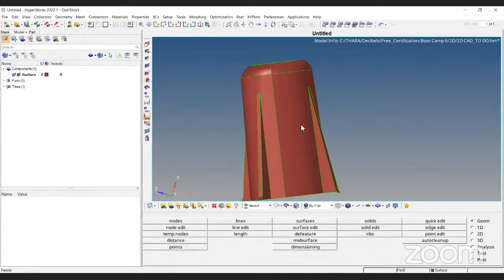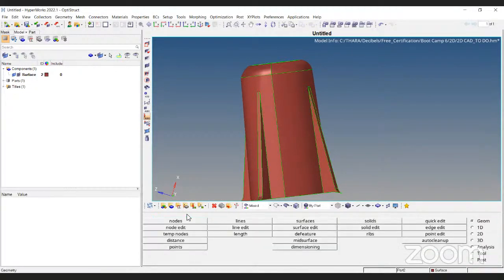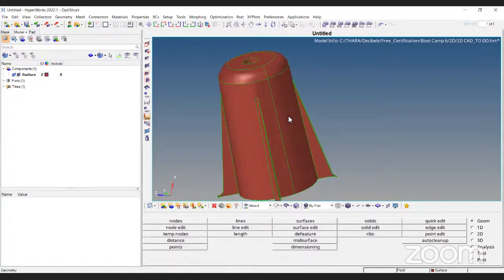And HyperMesh has function keys from F1 to F12, which are different shortcut keys as per the requirement. For example, F1 takes you to the help window, F2 is for deleting options, F3 for equalizing the nodes. From F1 to F12 there are different options. Using shift plus function keys F1 to F12, there are other predefined shortcut keys. You can make use of these.